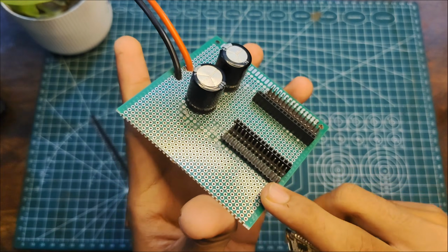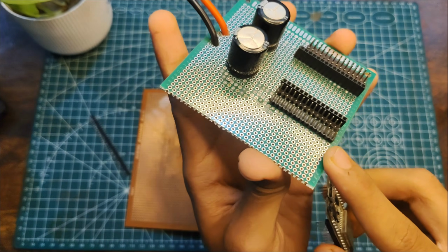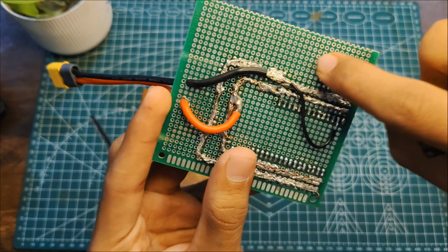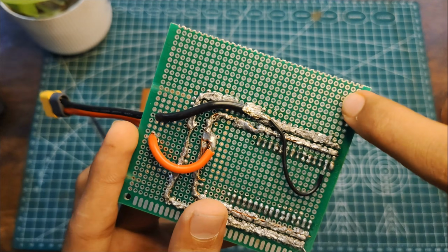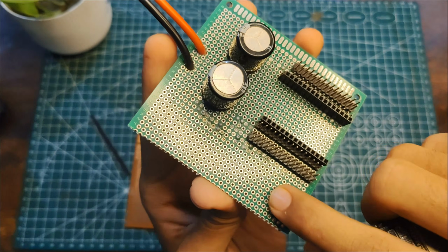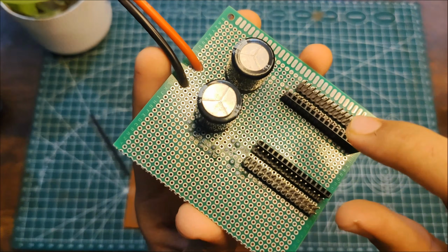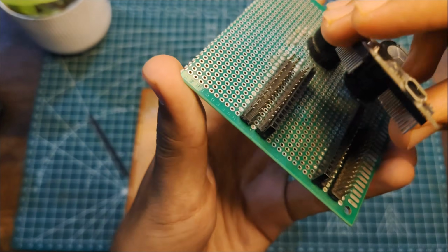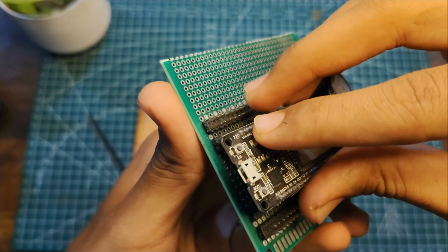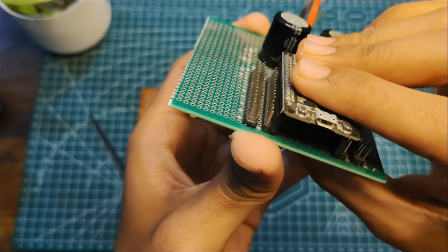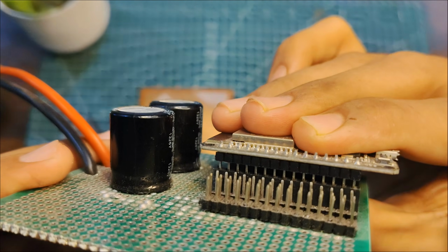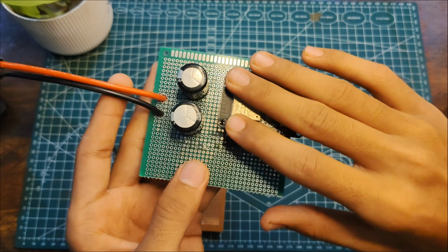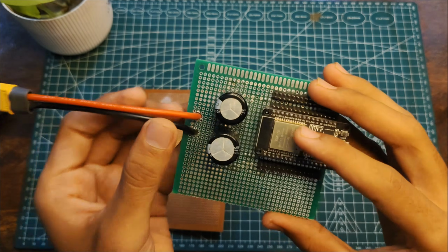So these are little costlier perf boards, and these are much better and my favorite one because they have extra strength, and you can see the silver pad or the soldering pad is on both sides. So I don't need to see which side is solderable or not. So I can simply put the ESP32 on top of this PCB I have designed. So I just need to put it on top of it and press it down, and we got our ESP32 on top of our circuit. So this is a small circuit that I have built for one of my RC cars.